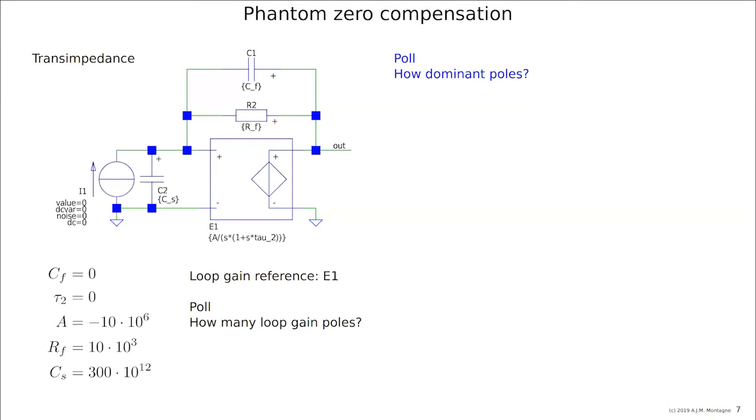You could rank the poles in the order of magnitude, and then check the first order, the second order, the third order bandwidth, etc., and take the smallest one. Or if a next pole is larger than the bandwidth you calculated with the previous one, it is not dominant. So let's see. The first pole is in the origin, at 0 hertz. But that doesn't mean that any other pole will be dominant, of course.